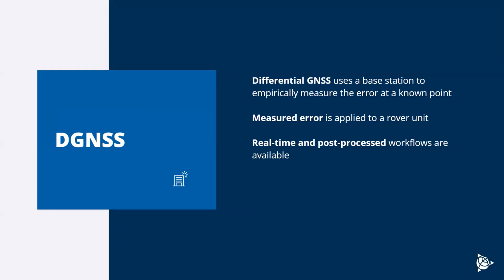Typically, when we're talking about GNSS in the field, for precision applications, we have something like a base and rover setup, where the base station is set up at a known location, and the rover unit is some sort of unit that somebody's using to mark unknown locations. Think about surveying, like a stakeout application, where you have your base station set up and your rover unit is a handheld device. You can go and measure locations very easily without having to lug around big equipment. We connect the rover unit to the base station either for real-time connections with a radio or internet connection, or we can do it post-process: collect 2 data files, come back to the office, and use processing software like TBC to get those precise locations that the rover unit recorded based on that base station correction.